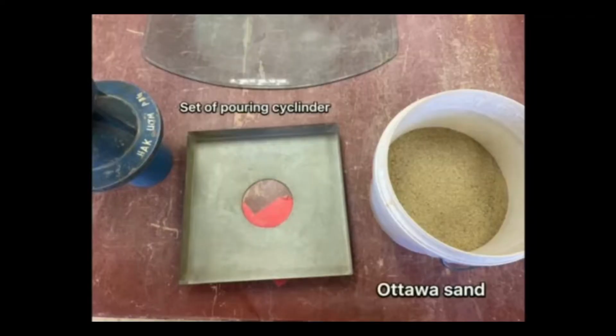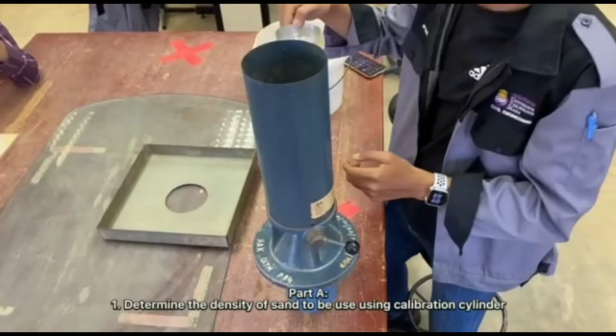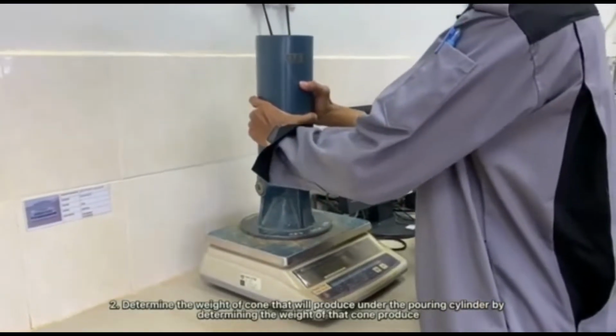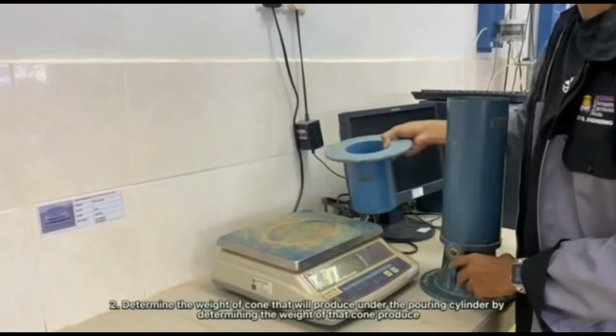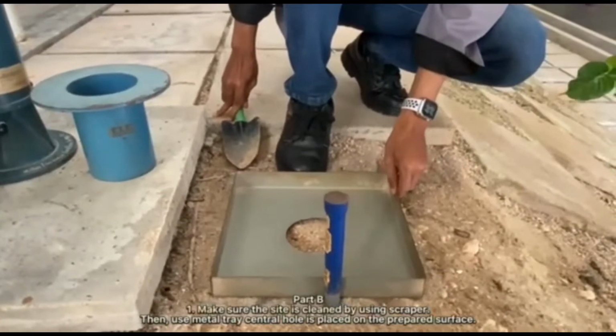The apparatus for this experiment is a set of pouring cylinder and Ottawa sand. For part A, we need to determine the density of sand to be used using a calibration cylinder. And next, determine the weight of the cone that will be produced under the pouring cylinder by determining the weight of that cone produced. For part B, first make sure the site is clean by using a scraper.